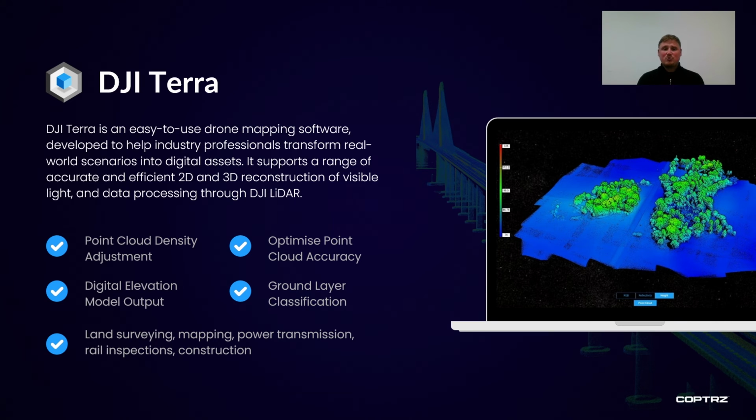Now, when it comes to LiDAR, there are many applications for that, but typically we always look at being able to penetrate through vegetation, utilizing it in a rail environment for, say, embankment surveys, but also looking at it from a power line, power transmission point of view, surveying power lines, things like line sag, that kind of thing. So many applications LiDAR can be utilized in.